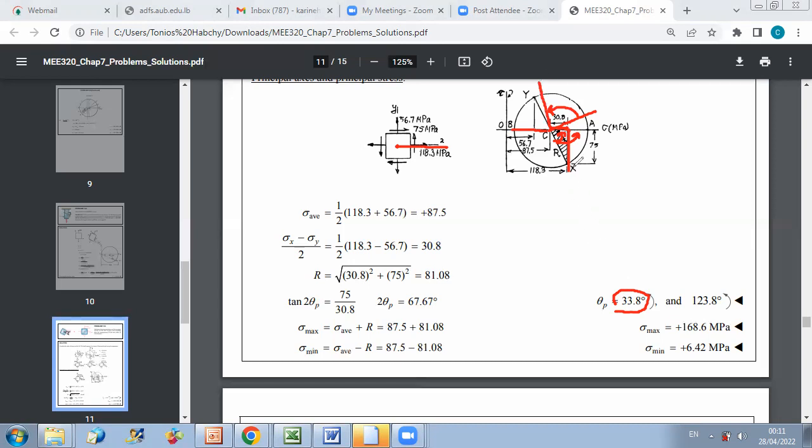And this corresponds to an additional rotation of 90 degrees, not on the Mohr circle, of course, but on the element. So on the Mohr circle, these are your principal axes. This is the first one, and this is the second one, corresponding, of course, to points with tau equal to 0. On the element, you have this.